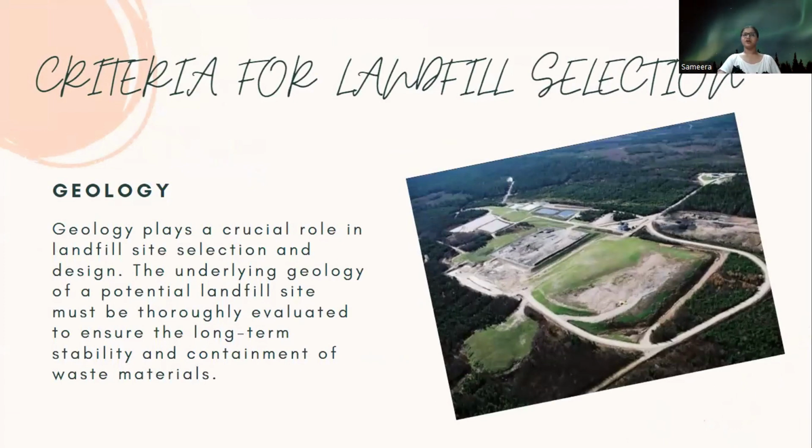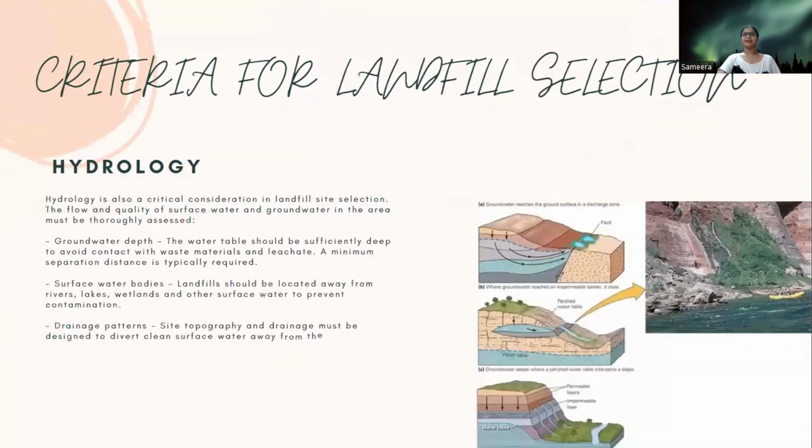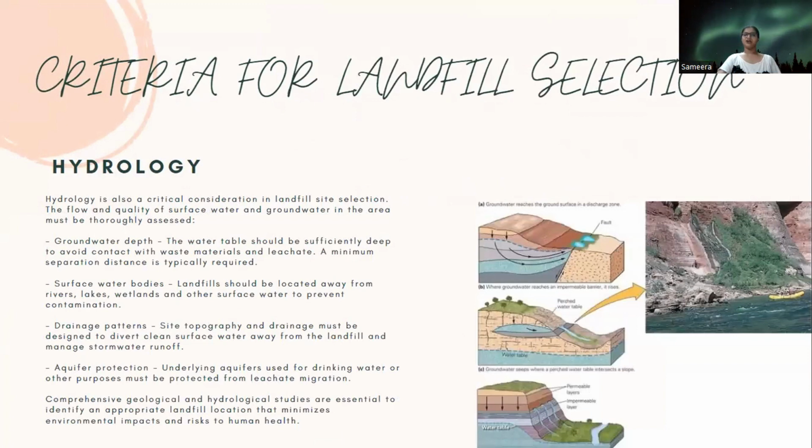Geology. Geology plays a crucial role in landfill site selection and design. The underlying geology of a potential landfill site must be thoroughly evaluated to ensure the long-term stability and containment of waste materials. Hydrology. Hydrology is also a critical consideration in landfill site selection. The flow and quality of surface water and groundwater in the area must be thoroughly assessed. Groundwater depth, surface water bodies, drainage patterns, and aquifer protection are some of the factors that need to be looked into.